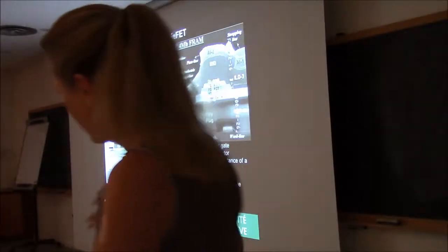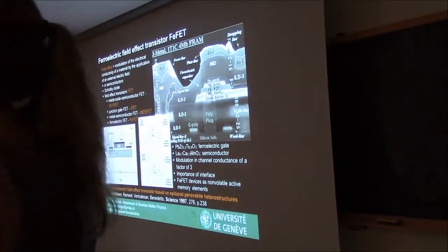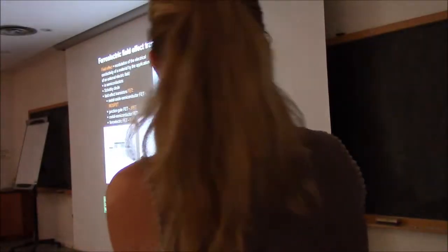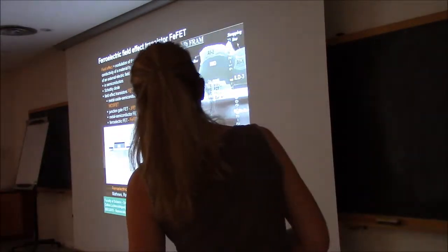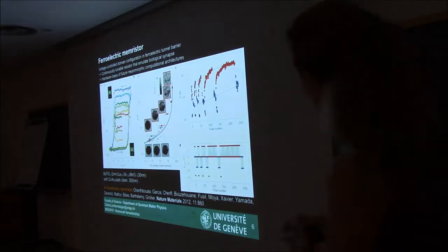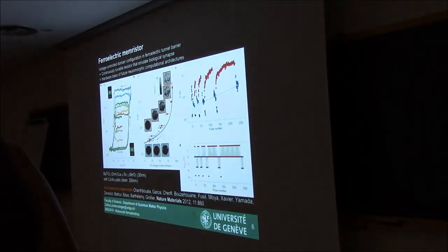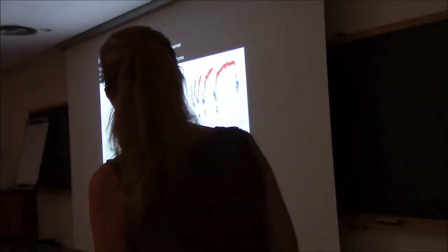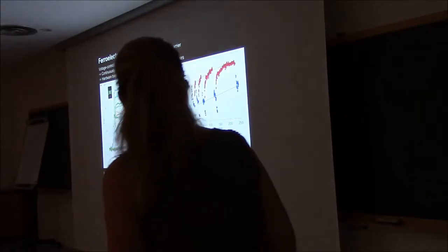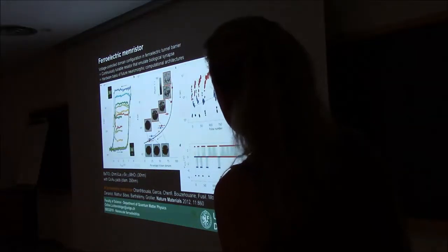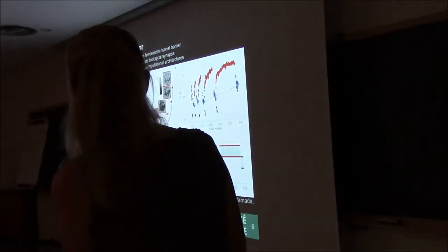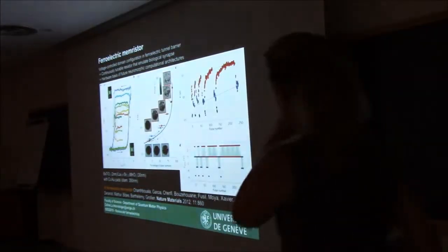So you see that we worked with nanoscale ferroelectrics already, but the interfaces and the electrostatic boundary conditions become more and more important. Another nice example from our very nice organizers is this device of ferroelectric memory store. The idea was to use barium titanate, just 2 nanometer layers of barium titanate with 30 nanometers of LSMO, and with some pads on top of it of cobalt and gold.